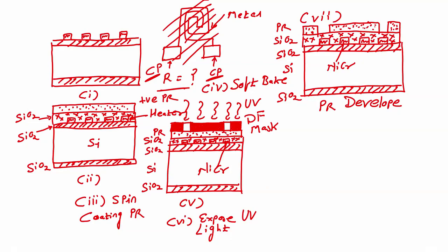Right. After that, what is the next step? We see that photoresist is protecting the rest of the area of the heater except the contact pads. So, now after this PR developer, I have to perform the next step, which is step number 8, your hard bake.